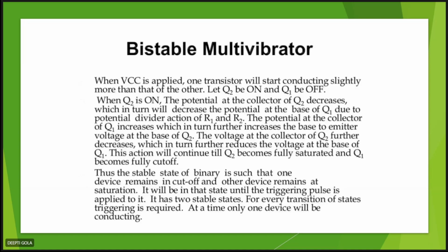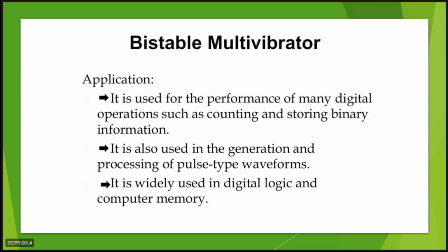I'm not explaining the whole process, you can now understand what is going on. So every time the transistor comes into a particular state, we have to provide the trigger to the other transistor so that the other transistor may be switched on, and the state of the output may be changed.